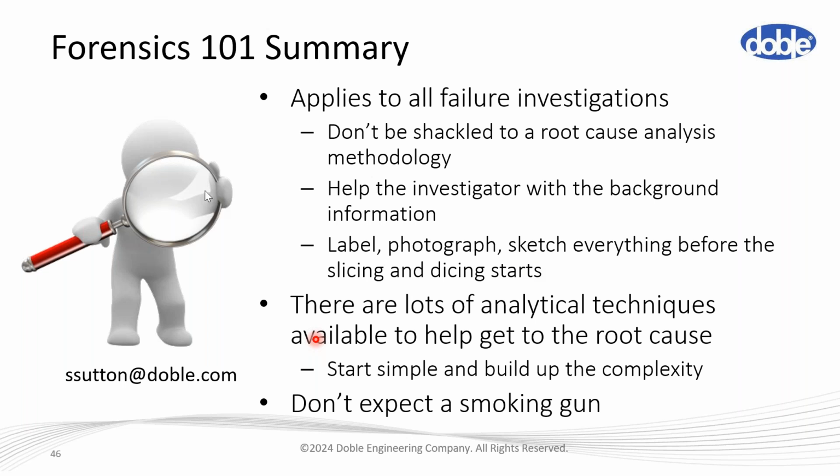Insulation resistance tests, can they detect the voids or cracks? No, I think that's going to be the simple answer there. You've weakened the insulation, but you would not detect it. It's a very small localized defect in a very long length of cable, so I don't think you would pick it up.